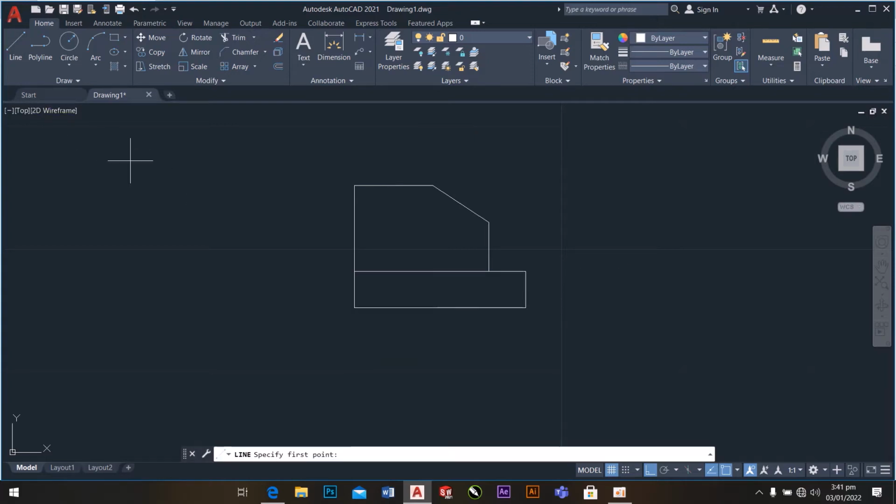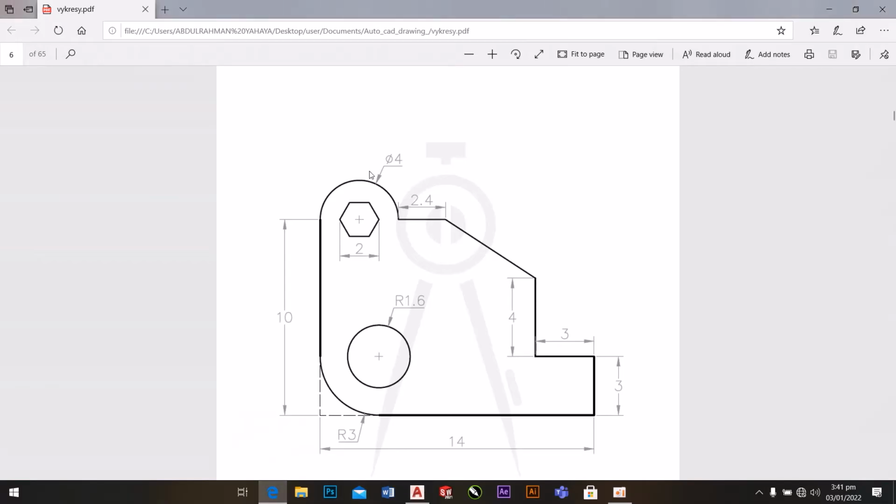and also draw another line. We can locate it to be 3, then bring it upward. Can delete this, extend this upward in order to get our other point. But the other circle there, we are given a diameter of 4 mm, which means the length from here to here is 4 mm.